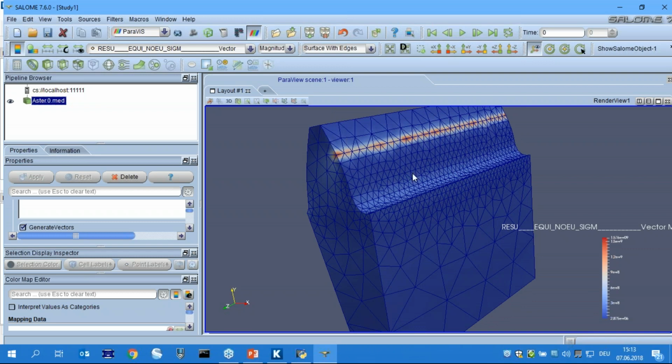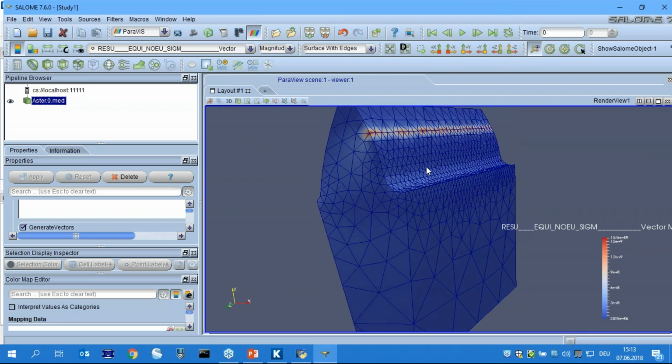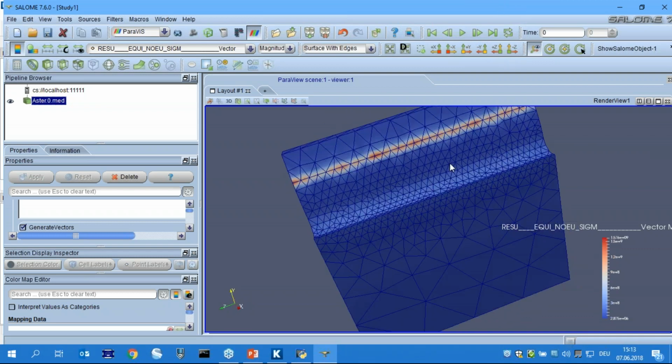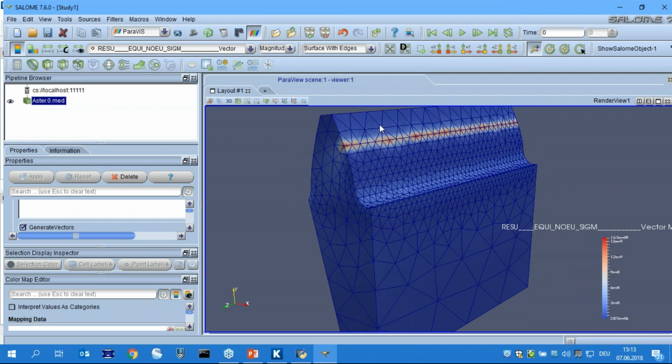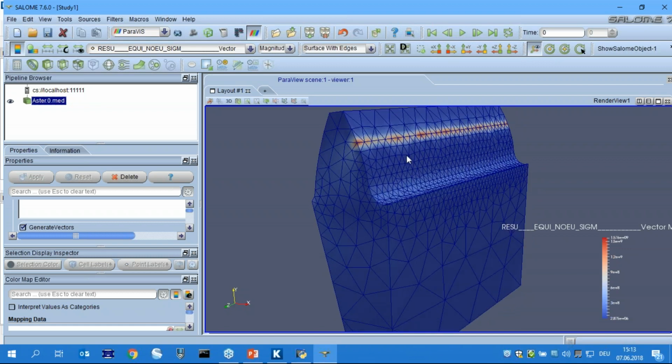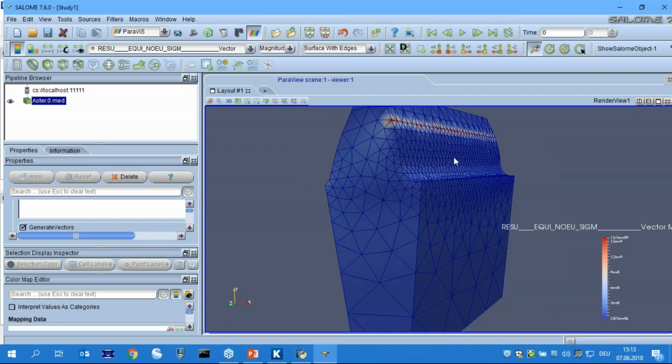Clearly, many customers also have an FE calculation tool, ANSYS or Abaqus, whatever, but this gives you an option to quite quickly, without setting any boundary conditions, without having to mesh it yourself, evaluate, in addition to the analytical methods, also with finite element methods, the stresses within the toothing.